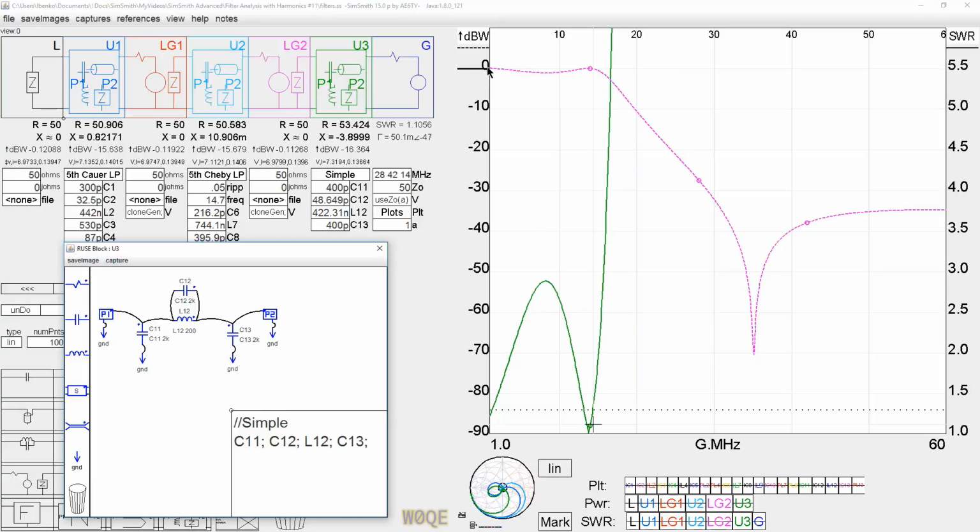We have a plot here of our output amplitude, and we can see that at our fundamental frequency we have about 1/10 of a dB loss. And that's assuming an inductor with a Q of 200 right here. We have a fairly narrow SWR passband here. And if we assume that this line right here at, I think it's 1.25 to 1, is all we'd ever tolerate for our generator, this would cover a range of 13.166 to 14.35 megahertz. I didn't exactly center it in the 20-meter band, but we can get the idea by doing this.